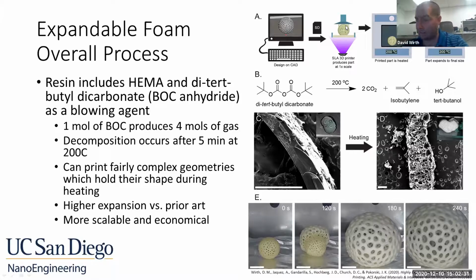And there's not a lot of monomers that are thermoplastic that you can 3D print with a photopolymer system. Like, as I said before, most photopolymer-based printing systems are thermoset, right? They're highly cross-linked, and most FDM, thermal-based systems are thermoplastic, right? So we had to find a photopolymer that was thermoplastic-based, which was very difficult, and find one that would dissolve a blowing agent, and find a blowing agent that would dissolve in this stuff, right? So it was a lot of trial and error.